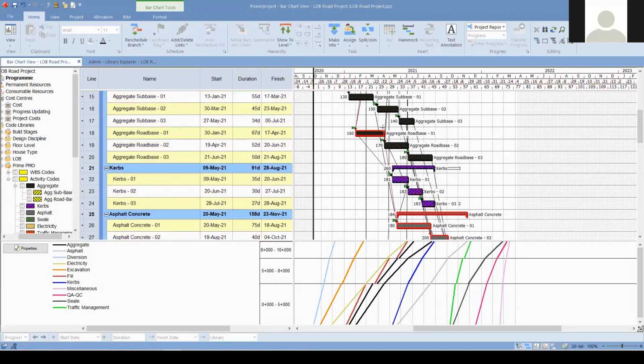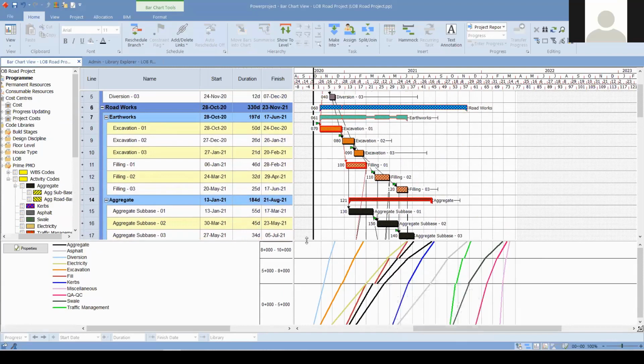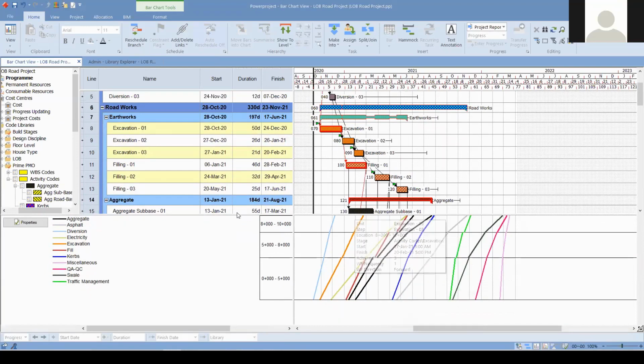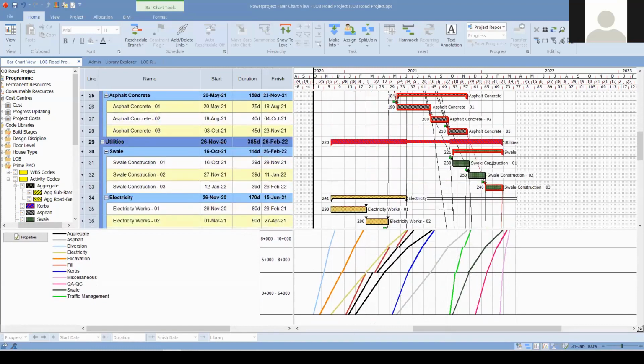Maybe after that we would like to update all the links and relationships according to line of balance, if and only if this schedule can be implemented in real time. So generally I would also like to recommend this approach as a what-if scenario. That is why you can save your original project schedule, implement the line of balance diagram, and represent all the activities in a single view. After that, you can change the start and finish dates and any relationships to maintain the activity flow without any stoppage, and so they do not collapse.